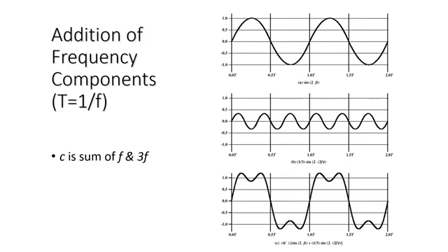Figures A and B can be combined to create a new wave that approximates a square digital wave, in which the formula for that wave is shown in figure C. The components of this signal are just sine waves of frequencies f and 3f, which are included in the formulas for the sine waves from figures A and B. Essentially, the wave in figure C is just the waves from figures A and B added together.